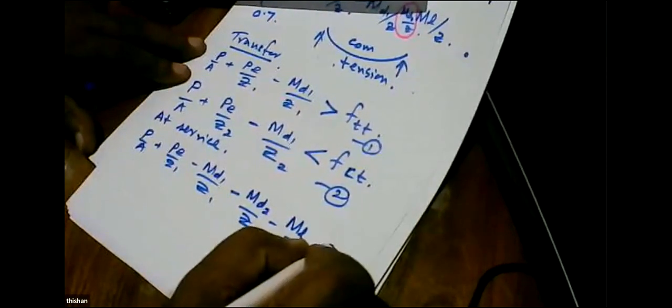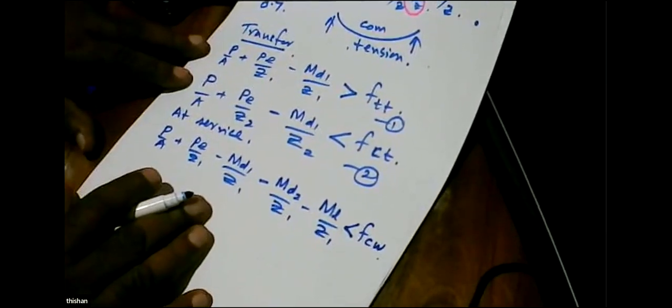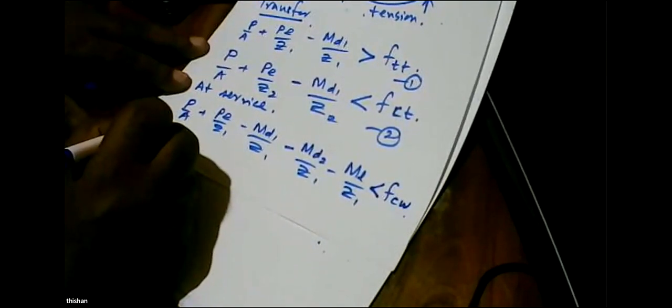So it should be less than the compression allowed under working conditions. Then you can write the same equation for the bottom fiber.